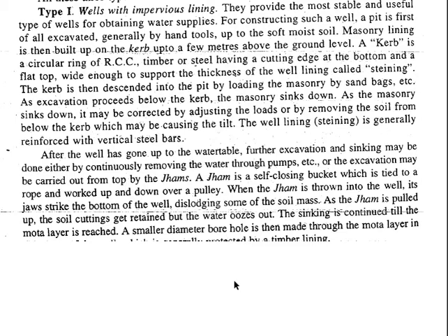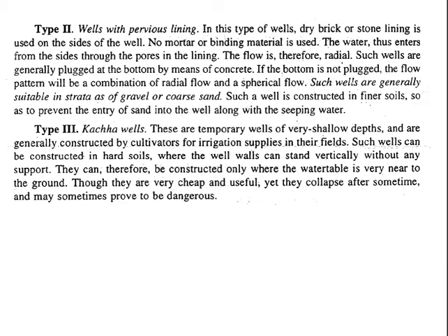So that's why it is being said that these are the wells with an impervious lining. But for the pervious layer, we don't provide the mortar or the binding material, which makes the water recharge capacity of this well, and that really improves its water recharging capacity.